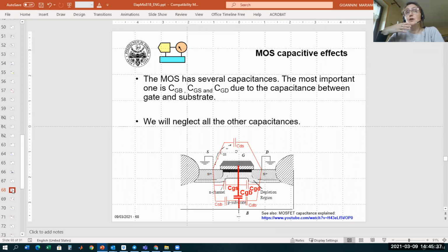It is as if we control the flow of water by controlling another parameter, in this case the VGS voltage. But there's not only this behavior like a resistor controlled by the gate voltage; inside the structure we have many additional parasitic capacitances. We can't avoid them.